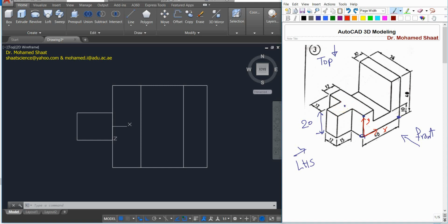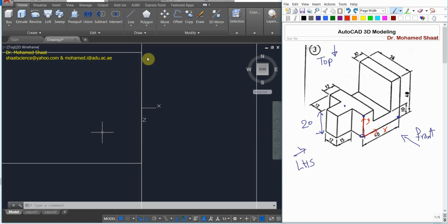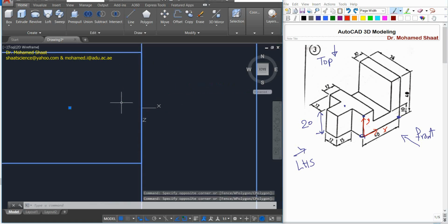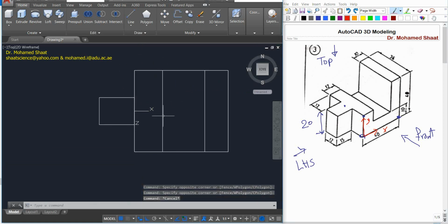It means that there shouldn't be any line. There is no line here, right? Slicing this T shape, it should be like a single face. But looking at the AutoCAD side here, I'm seeing a line in the middle. You cannot remove it. Even if you use trim, this line won't be removed. Why? Because now it is not a two-dimensional sketch, it is a 3D solid. But this line is there.